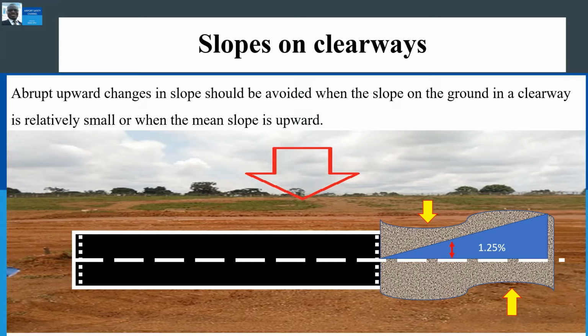It is not intended that these surfaces should be graded to conform to the lower limit of the Clearway plane, nor is it intended that the terrain or objects which are above the Clearway plane and beyond the end of the strip but below the level of the strip limits be removed, unless it is considered that they may be endangering aircraft operations. If you look at the picture on the screen, you can see that the area beyond the strip is higher than the strip, which means that it's above the Clearway also.